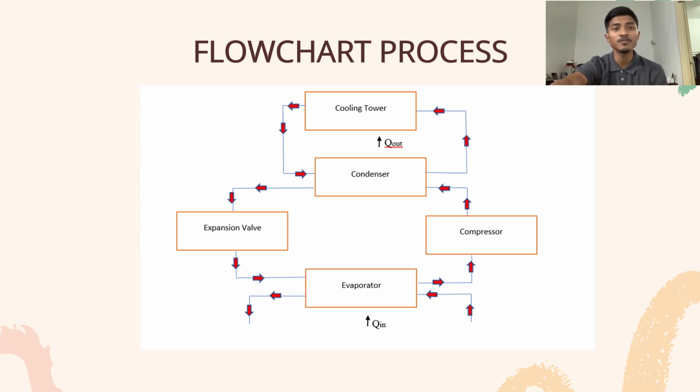The expansion valve performs two functions. It controls the flow of liquid refrigerant between the condenser and the evaporator while dropping the high pressure refrigerant to the lower pressure used in the evaporator. The evaporator, a heat transfer device, allows the low pressure liquid refrigerant to absorb heat from the indoor air, changing the refrigerant into a low pressure vapor.